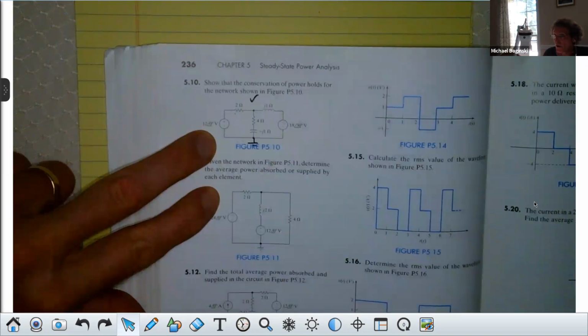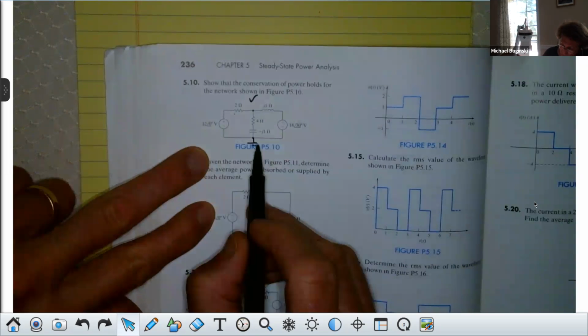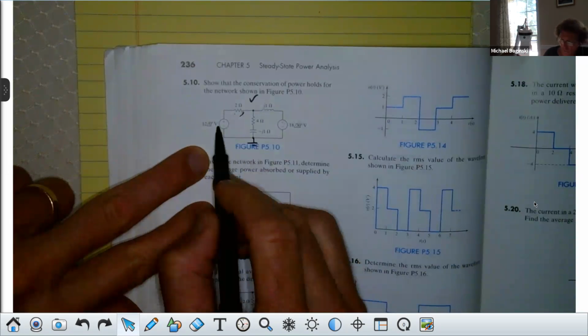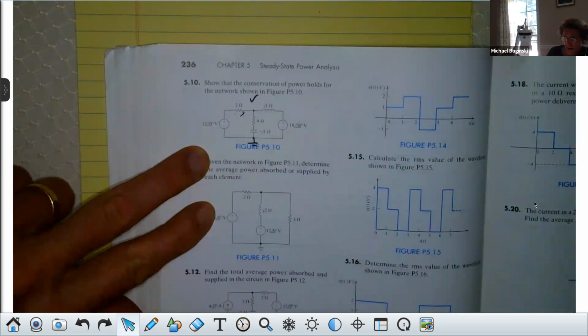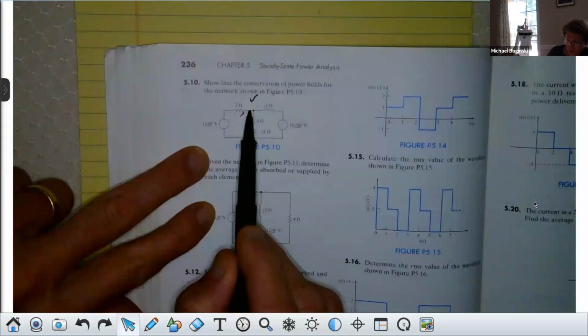One equation, one unknown. Are you with me? I'm trying to save time, so just listen. Now, if I put a ground there, wouldn't I get the current through here? It would be 12 minus V, right, over 2. I'm trying to talk very slowly. 12 minus V over 2 ohms would be this current, right?